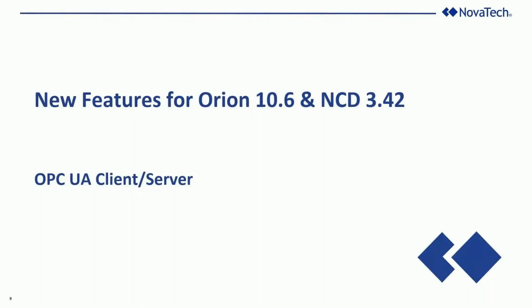Certainly. Someone asked, and I should have mentioned during the presentation, that the MX can only use one E1 card. You cannot fully populate the Orion MX with multiple E1 cards. It only allows one. And someone else asked what the polling rate of the Mega card was, and that is set for 2 seconds.